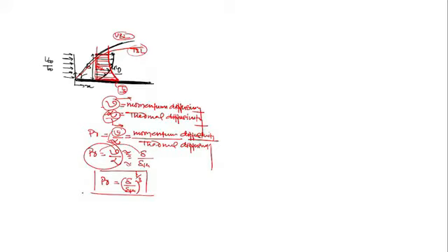And when the Prandtl number is less than 1, it means heat diffuses faster, then obviously the thermal boundary layer thickness is more than the velocity boundary layer. And if the Prandtl number equals 1, then both thicknesses are the same. Clear? So which thickness is more is decided by the two terms, momentum diffusivity and thermal diffusivity. Clear?